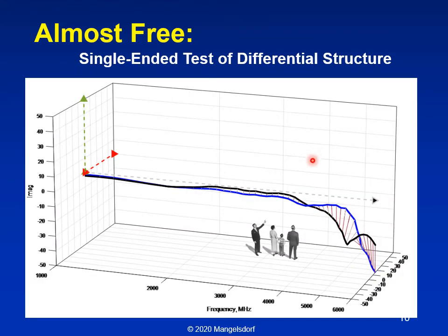This shows an example of doing that test that shows you how the harmonics change with the input frequency here. And you can see along the horizontal axis is the input frequency, and then the vertical and into the screen axis are the polar coordinates of the harmonic itself. And you can see that at low frequencies, of course, both harmonics are very small and very similar, but at higher frequencies, they become more and more different. And this is very useful for you to know.